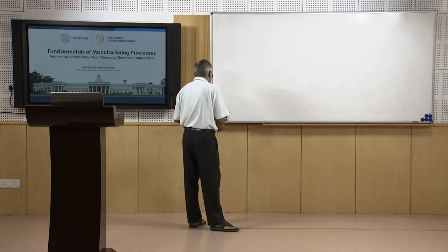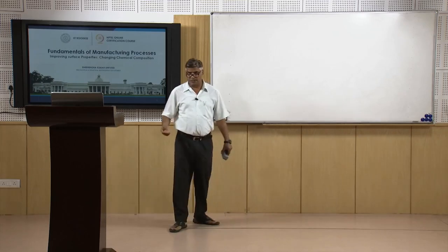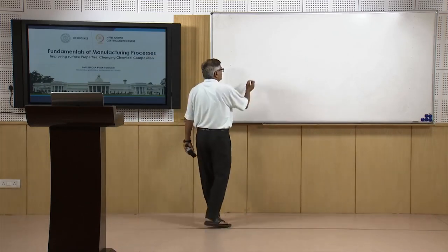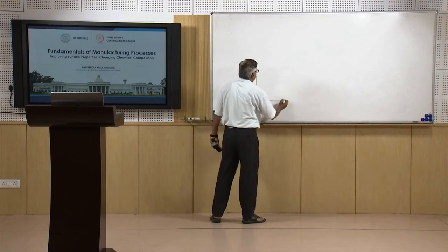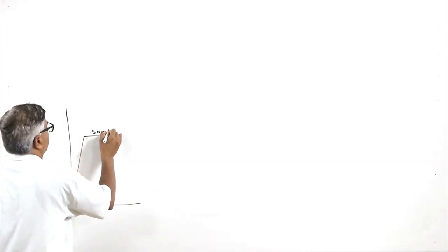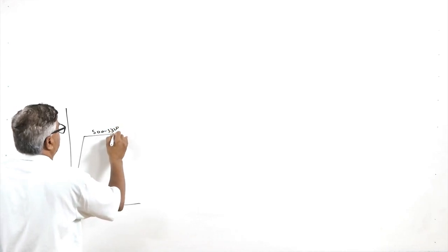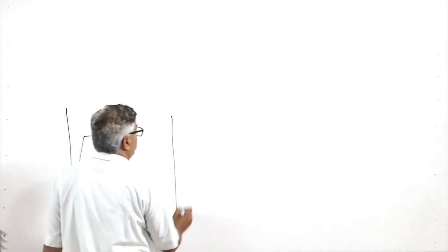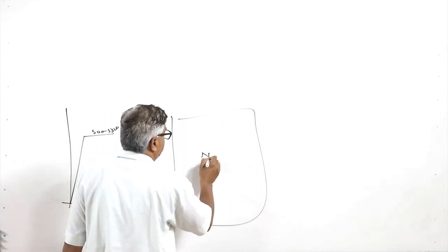While in the case of nitriding, the approach is different. Nitriding is always carried out in the ferritic state. So, normally the heating is done up to a temperature of 500 to 550 degrees centigrade, and of course in a nitrogen rich environment. So, in a box basically ammonia is heated.